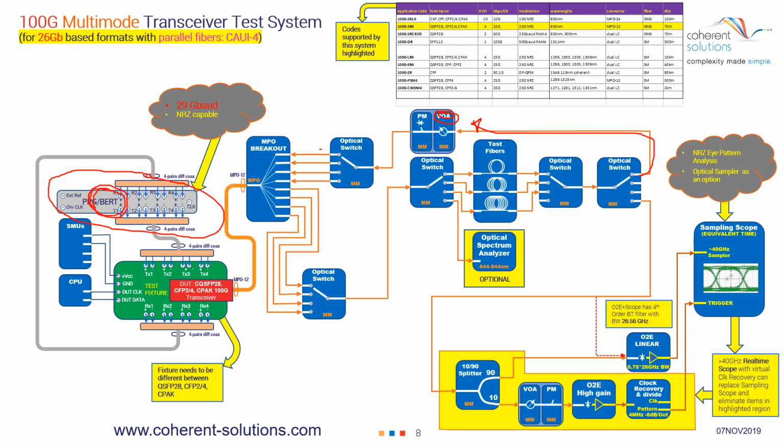This allows you to determine the sensitivity of that particular receive path. By selecting one at a time each of these receive paths, you can stimulate each of the receives. Again, you can transmit any one of these transmits to the other receiver. Traditionally, the transmit for channel number 1 will be used to stimulate receive channel number 1, and so on. Transmit channel number 2 will be used to stimulate receive number 2. Okay, so that's the bit error rate path for sensitivity on this particular slide.